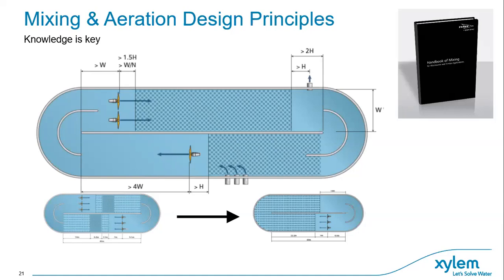So in these scenarios, that does mean that aeration systems are being oversized, and as a result, that oversize does lead to over aeration, which obviously is the point Magnus is making, that when we over aerate, we're wasting money to essentially mix using diffusers rather than technologies like mixers. So that's a really important thing to be mindful of when completing process designs.